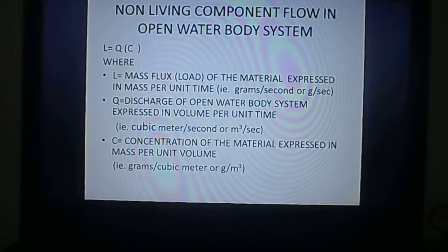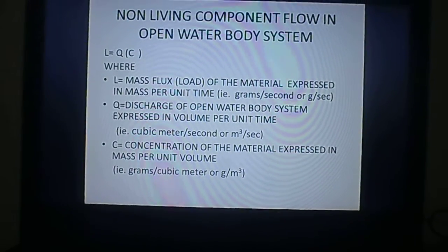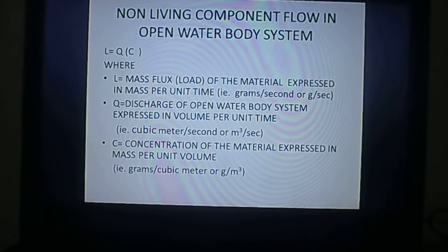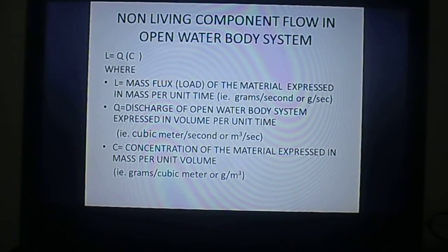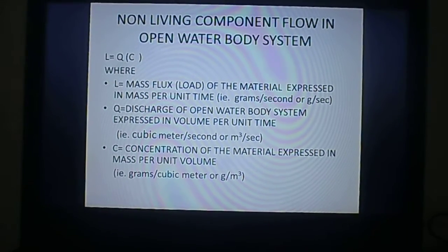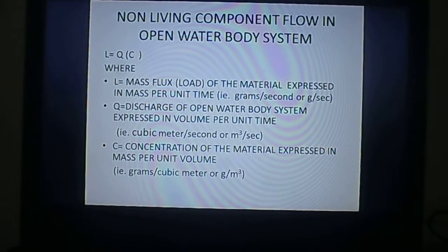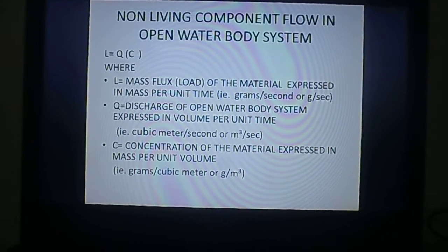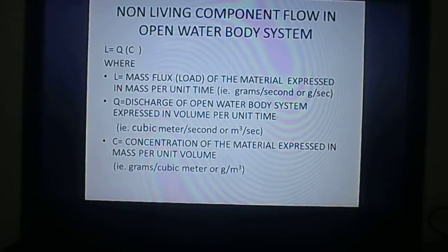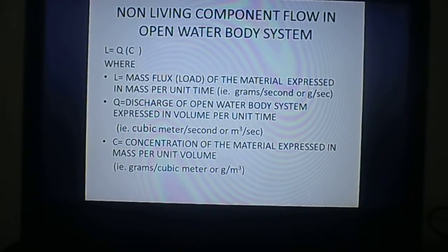C in the expression L equals Q times C is concentration of the material expressed in mass per unit volume, and therefore grams per cubic meter may be the unit of the C, where grams is unit of mass and cubic meter as unit of volume.